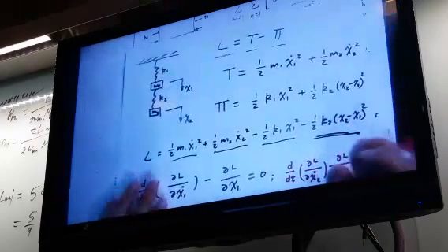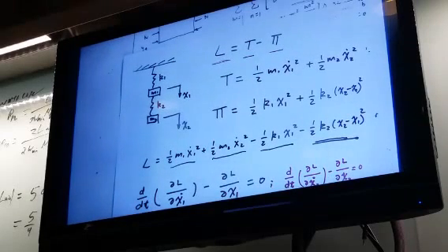And potential energy for this spring mass system is associated with the springs only. The two springs, each spring is elongated. You just use 1/2 Ku squared. This is the definition for the potential energy of the spring, right? So for the first spring, this is the elongation, Ku squared divided by 2. And for the second spring, this is the elongation, x2 minus x1, because they are elongated in the same direction. So the total elongation of the second spring will be the difference between these two ends. And then you can form the Lagrangian function of the whole system.